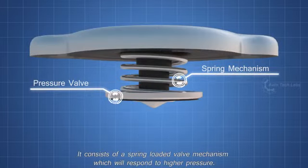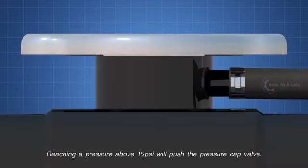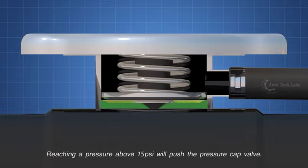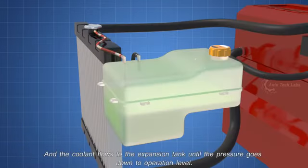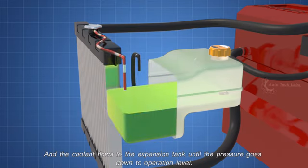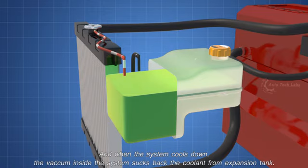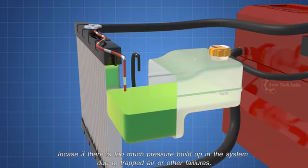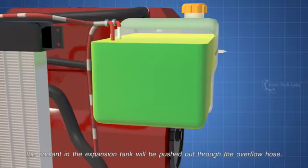It consists of a spring-loaded valve mechanism, which will respond to higher pressure. Reaching a pressure above 15 psi will push the pressure cap valve, and the coolant flows to the expansion tank, until the pressure goes down to operation level. And when the system cools down, the vacuum inside the system sucks back the coolant from the expansion tank. In case there is too much pressure buildup in the system, due to trapped air or other failures, the coolant in the expansion tank will be pushed out through the overflow hose.